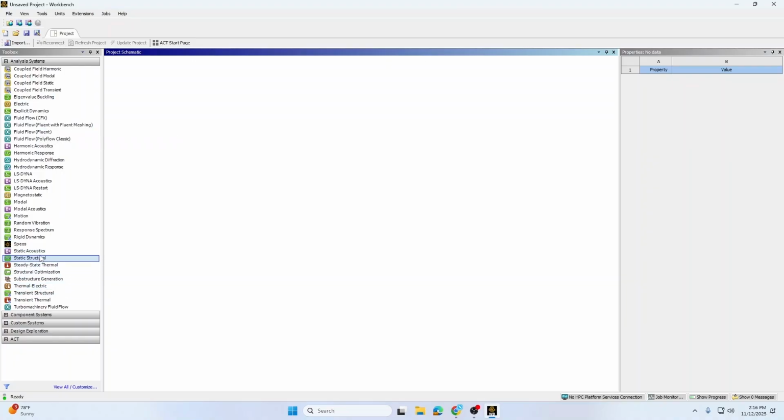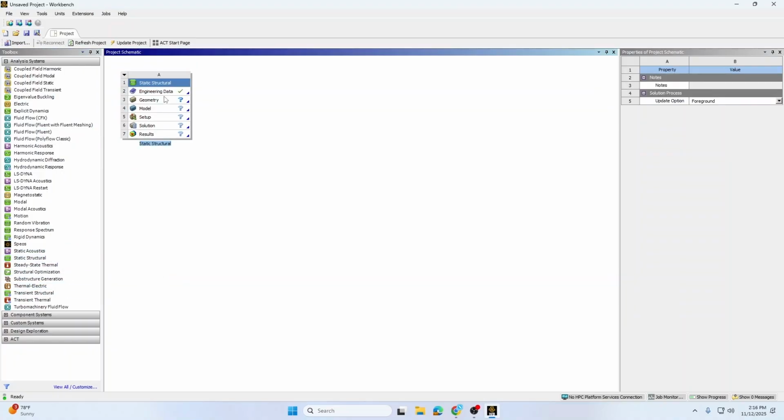All right, now that ANSYS is loaded up, the type of analysis we want to perform is called static structural. So that means that our solution doesn't have anything moving around, and we are just looking for applying some forces, getting out the deformation and stresses on that object.